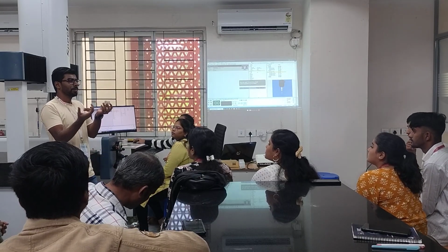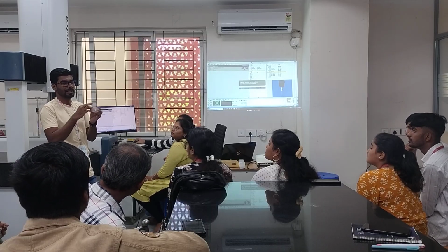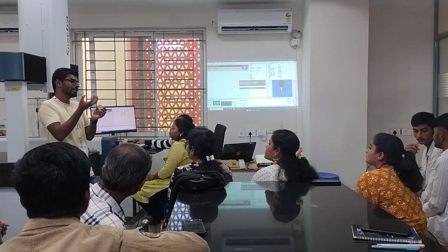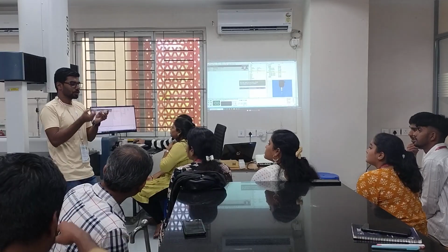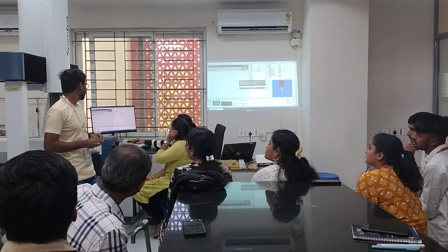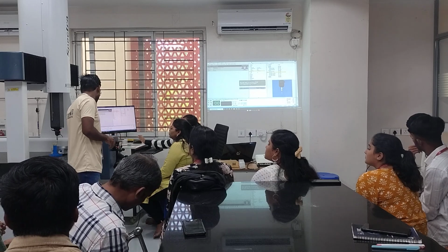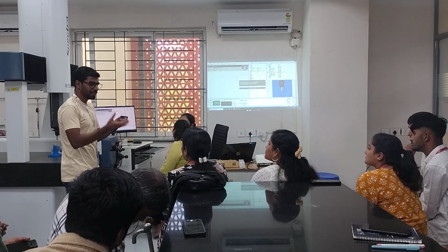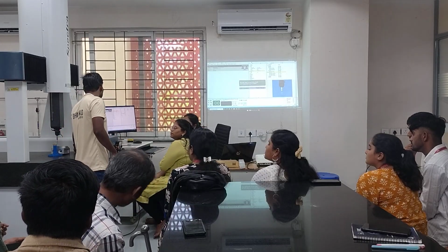Because whenever you are printing in DLP as well as SLA, there is some shrinkage happening. Printing is happening at some higher temperature. The resin is already heated. So when there is a cooling of temperature, it shrinks actually. So that shrinkage is visible here in the form of 39.39 something. So this is a proof that yes, it shrinks. And we'll compare how much FDM shrinks, how much DLP shrinks, and how much this composite shrinks.